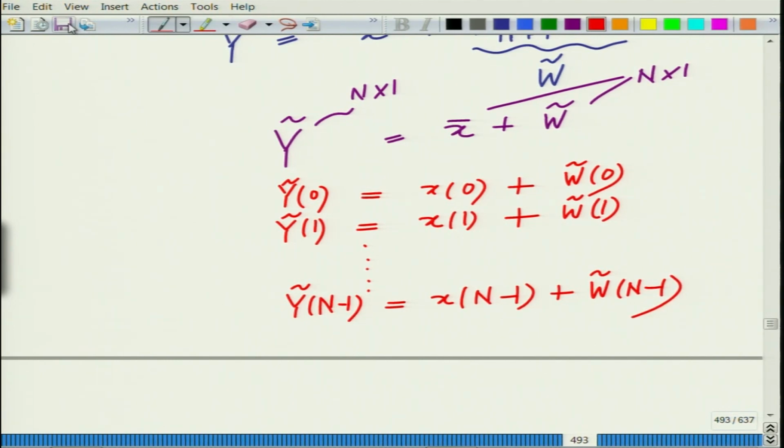Now, why go through all this frequency division multiplexing when you want to simply transmit using a single carrier? The advantage is you still have a decoupled system, and more importantly the equalization can be performed using the FFT and IFFT operations. This is not possible in a conventional single carrier system.